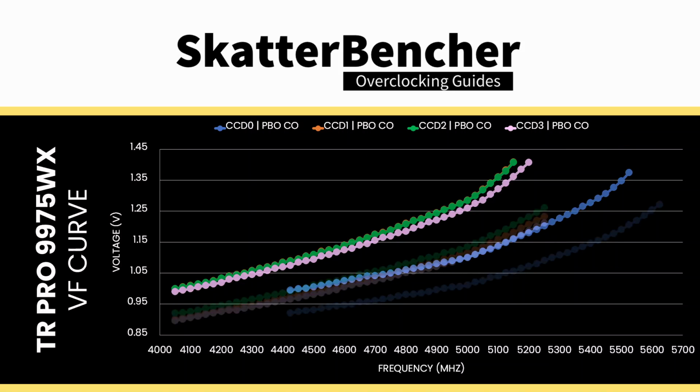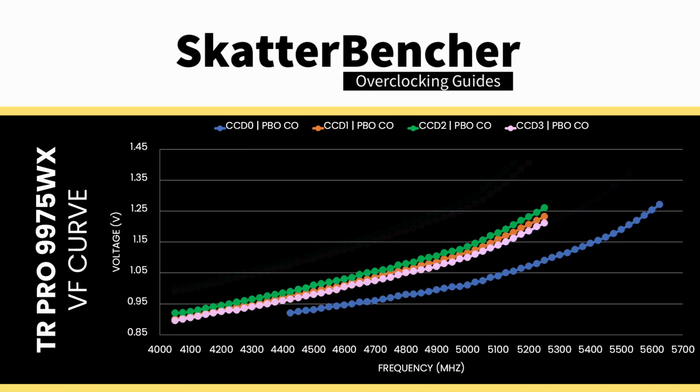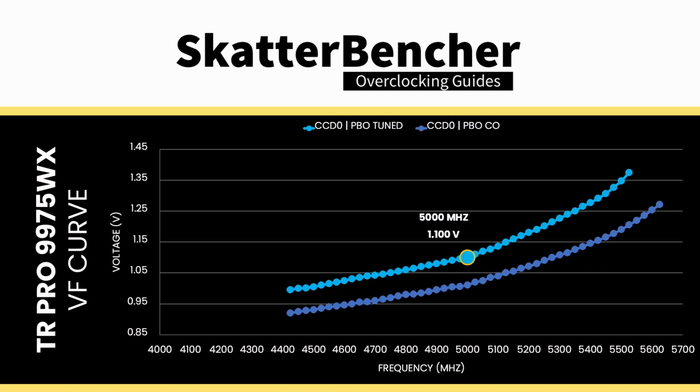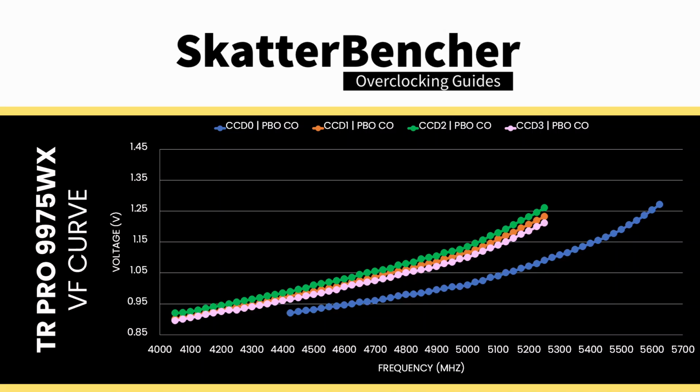If we set a negative curve optimizer, we can shift the entire voltage frequency curve along the voltage axis, and suddenly we need less voltage for every operating frequency. For example, at default, for 5 GHz, CCD 0 needed about 1.1 volt. However, with a -30 curve optimizer, now we only need 1.01 volt. And the same observation applies to CCDs 1, 2, and 3. Moreover, the frequency is also boosting higher. The highest frequency with all 32 cores active has increased to 5625 MHz on CCD 0 and to 5250 MHz on the other CCDs.